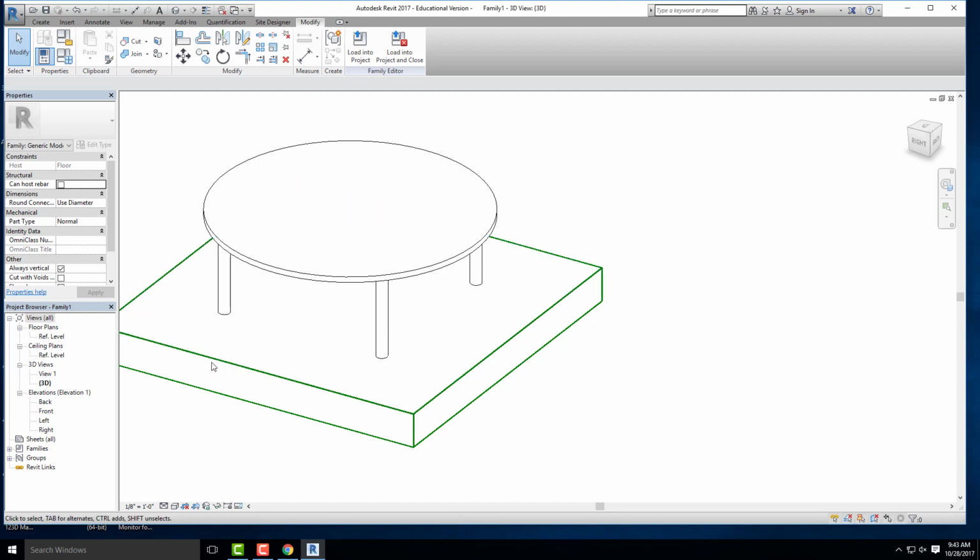Okay, you could actually start building this plate if you wanted to using the ground reference plane, but what makes it difficult is, as you keep going up, you're now thinking of the bottom of your reference plane as 2'8". Okay, so you're starting to add all of the little increments on top of 2'8" versus starting at 0, 0.